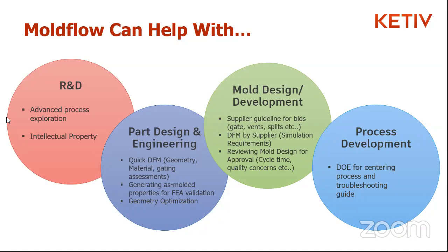So the geometry that you're creating for this component, the material selection process has a big impact, and then where you can and can't gate it. So not to say that you can't create other issues downstream here with a bad mold design, bad feed system, or cooling, or bad process. Certainly can. A lot of times, though, it's aggravating those three big variables: geometry, material, and potential gate locations.